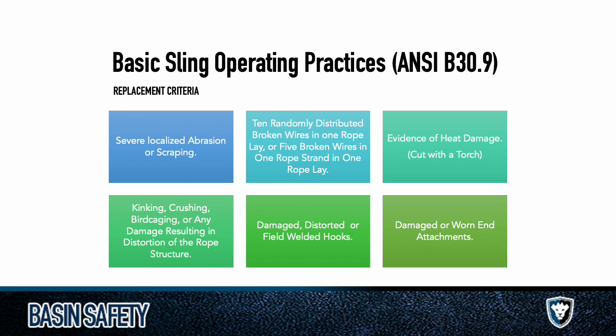Usually, you're going to see abrasion where it's rubbed against something, or it started to tear because it's been over its capacity, or it's just been stored improperly. Weather conditions will break it down over time. Water can break it down. Chemicals can break it down, etc.